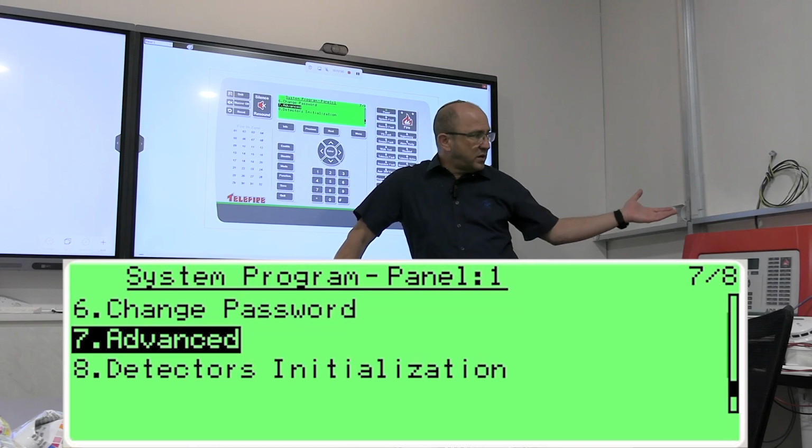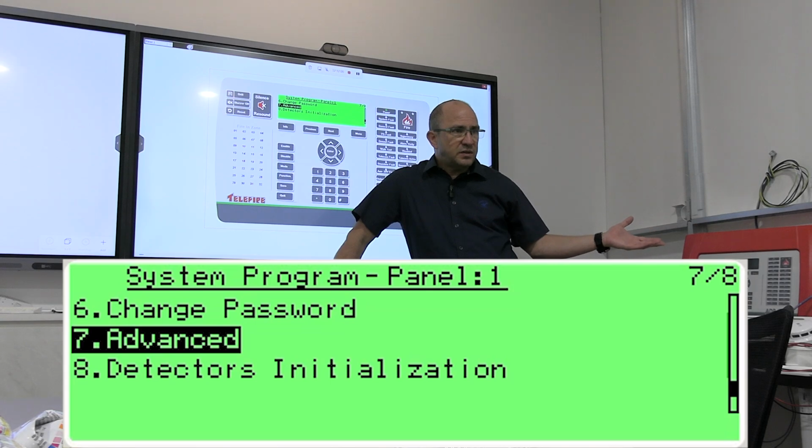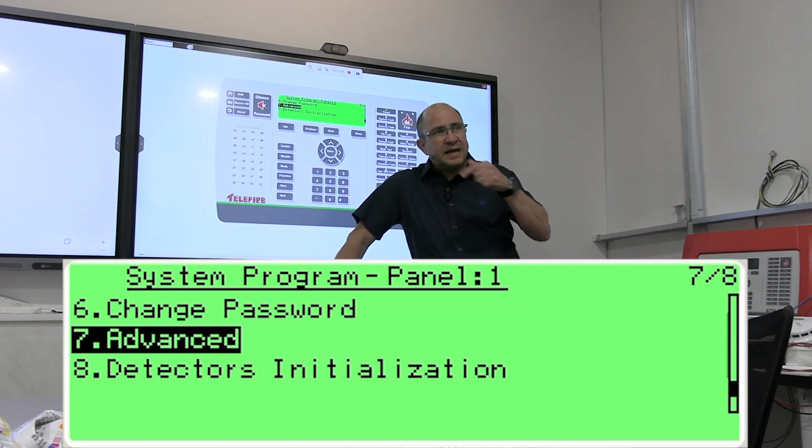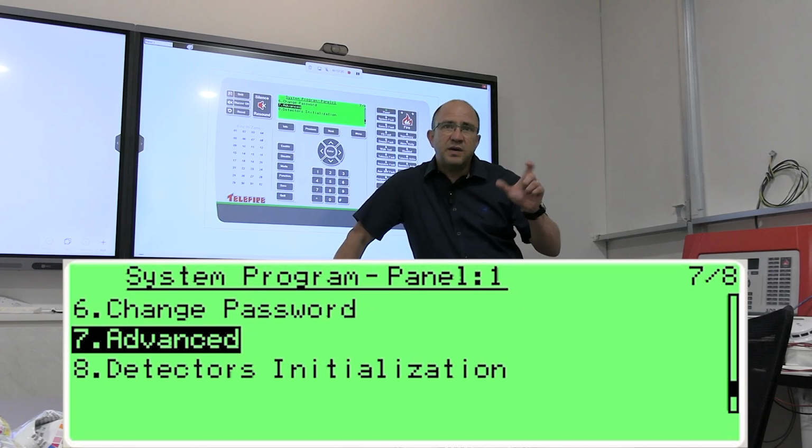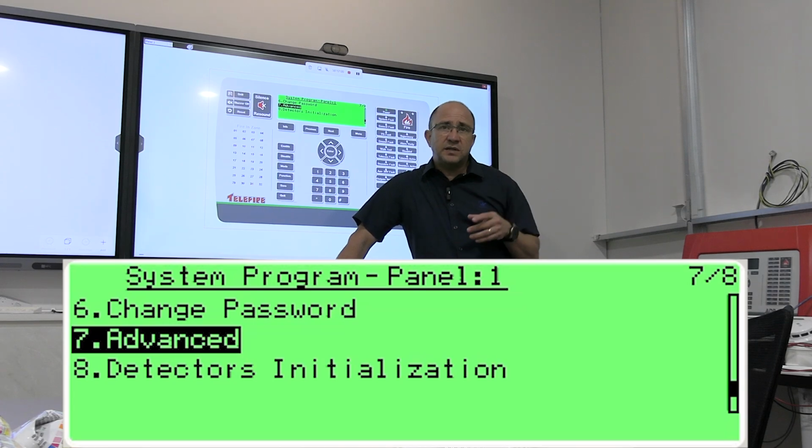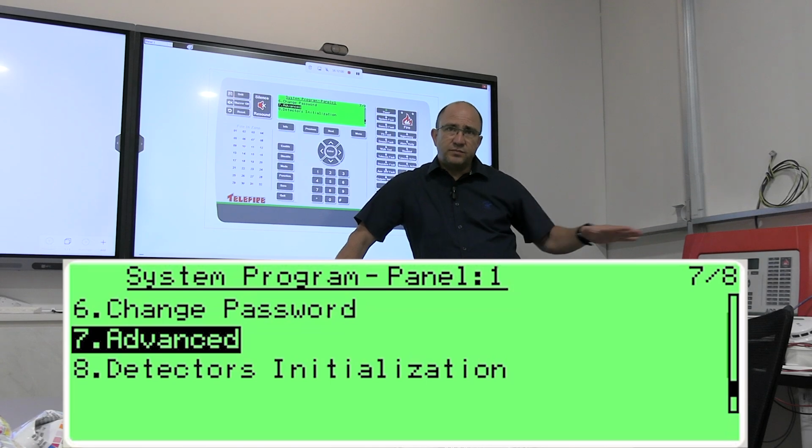Because every control panel needs the batteries, and if I disconnect the batteries, I have to know about it. But I told it, don't take any notice. That's an example for illegal. But I did it because I go overseas, I don't have batteries. So it doesn't check the batteries. And also ground fault it doesn't check, because I have exactly what you have here inside the demo kit, the suitcase.